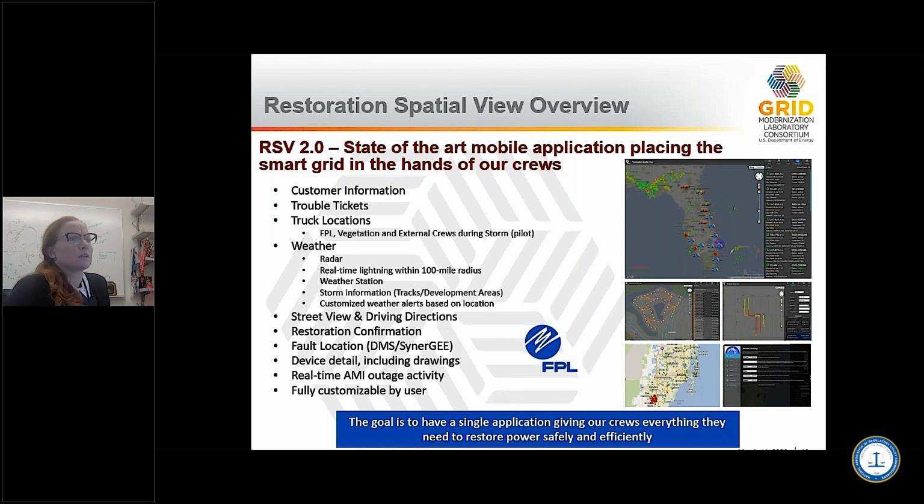One of the really interesting things that came out of this was being able to see the voltage data from the smart meters. It enabled them to see that there was a set of components that had erroneous voltage data, which was all co-located with a certain type of transformer from a manufacturer. And it turned out that those all had a particular issue that meant they needed to be replaced or repaired in the near term. So giving some basic visualization can take us pretty far, but being able to integrate it is still an ongoing issue that everyone is working on as well. So, next slide.